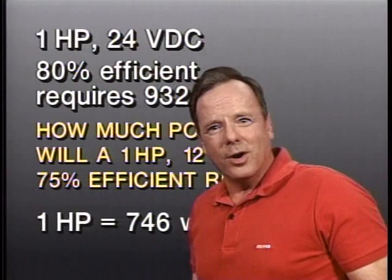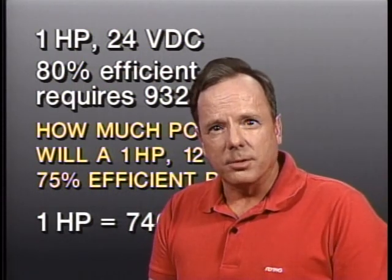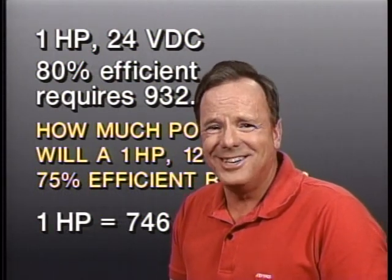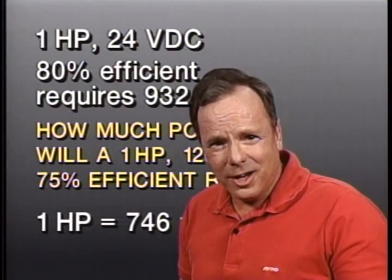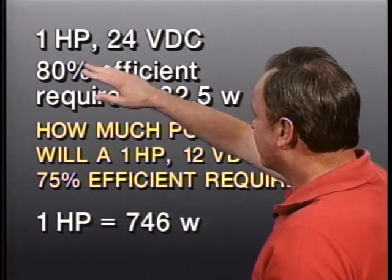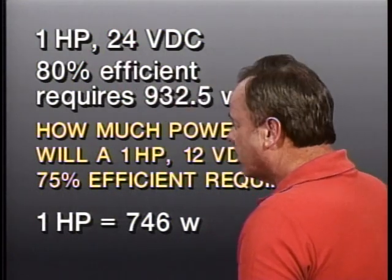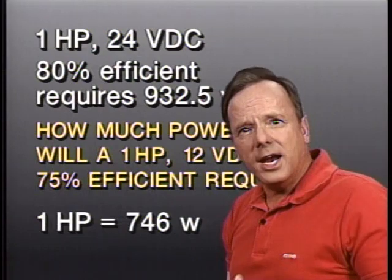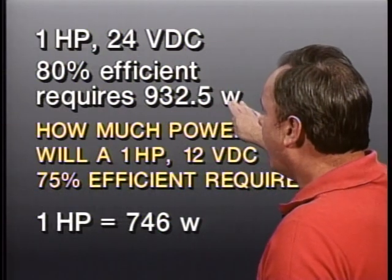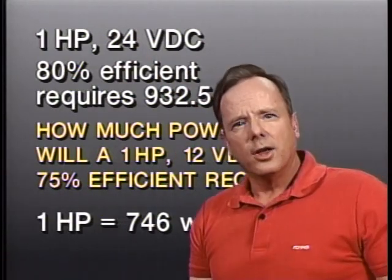Now let me ask you a question. Do you think that even in the most remote stretches of your imagination that the FAA could ever be deceptive? You bet they can, and here is a case in point. They have a question like this, they give you this information. They tell you that you have a 1 horsepower, 24 volt DC electric motor, and that this electric motor is 80% efficient, and it requires 932.5 watts to produce that 1 horsepower. They give you that information, then they ask you this question.